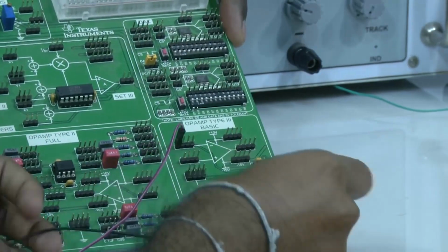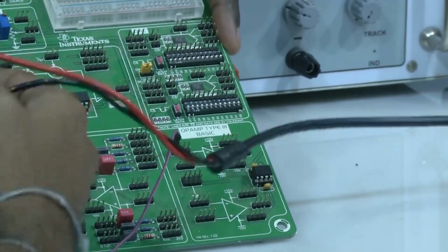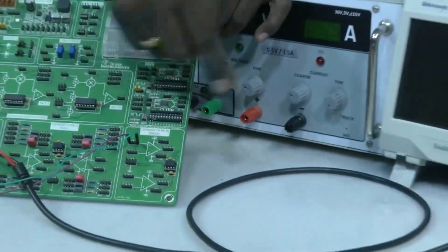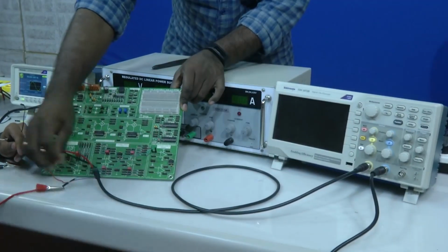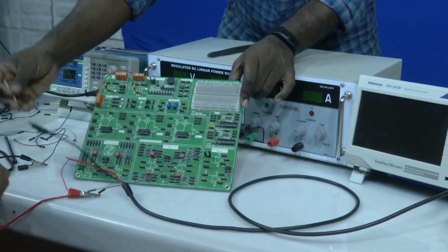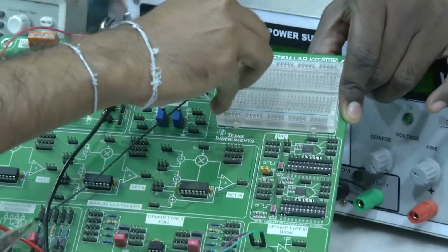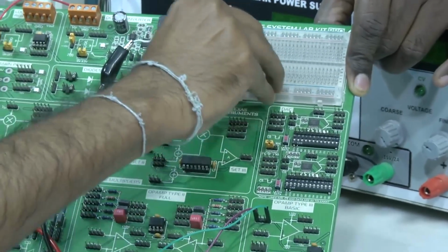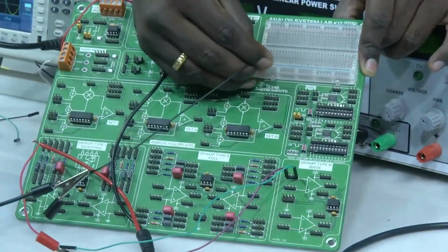In order to visualize both the input and output on the CRO, one connector from the CRO. So, in order to visualize our input signal, one channel of the CRO is connected to the input. Here we can see one channel is connected to the input. Now the grounds of both should be shorted. So, we will use the breadboard. All the grounds we will connect to the negative terminal here. So, negative is ground for us, and all grounds we can make common. So, we are connecting to ground.